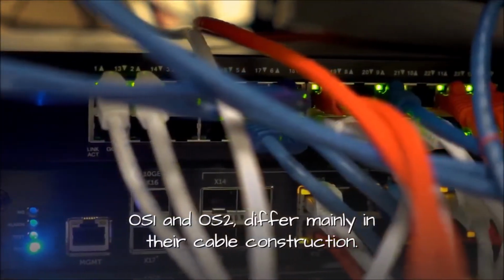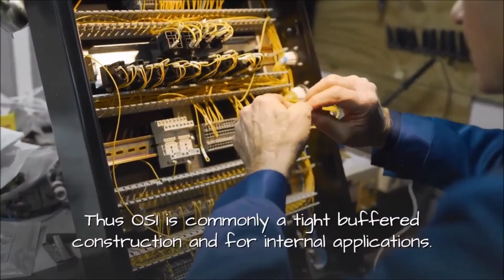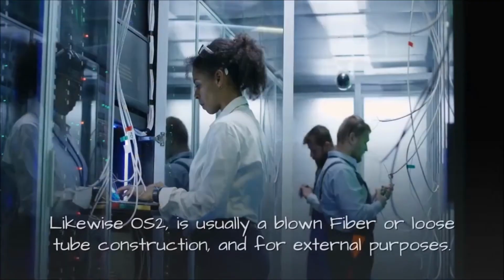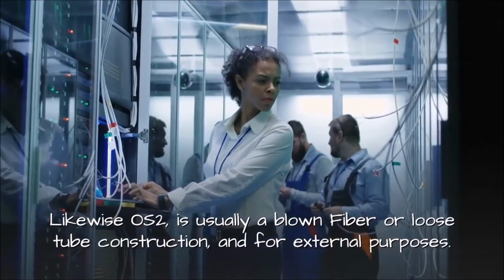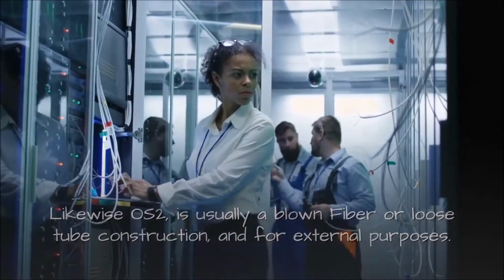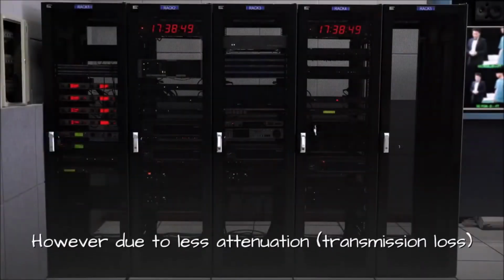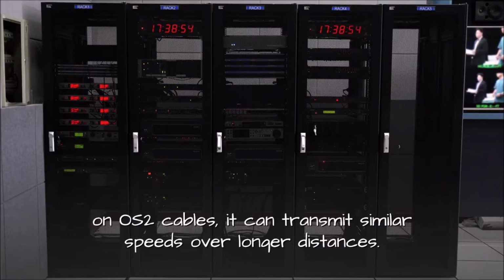OS1 and OS2 differ mainly in their cable construction. Thus OS1 is commonly a tight buffered construction and for internal applications. Likewise, OS2 is usually a blown fiber or loose tube construction and for external purposes. They have similar transmission characteristics. However, due to less attenuation, transmission loss, on OS2 cables, it can transmit similar speeds over longer distances.